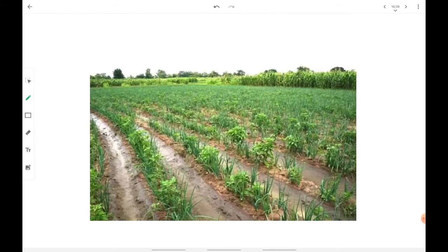This is how the border strip irrigation method looks. On the upper strips, we have planted the crops. The channels, the grooves, the borders, meaning in between the borders, the water is allowed to flow. The water is going to percolate into the layers of soil, and then the plants planted on the strips are going to avail the available water.